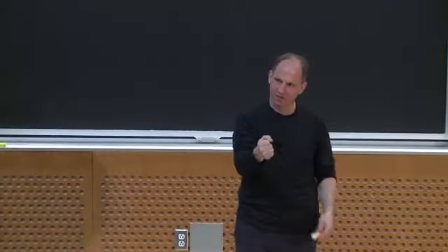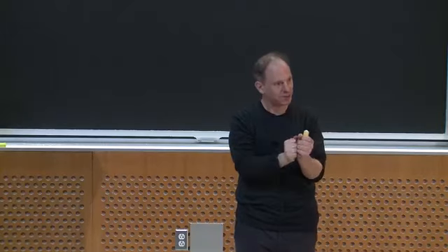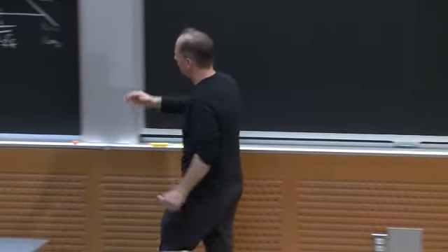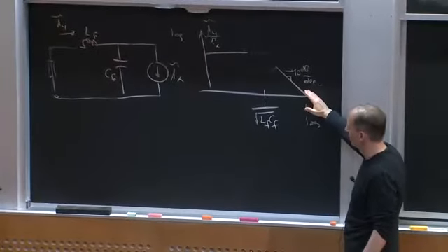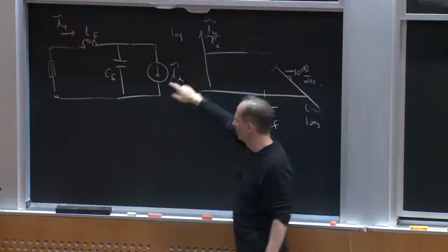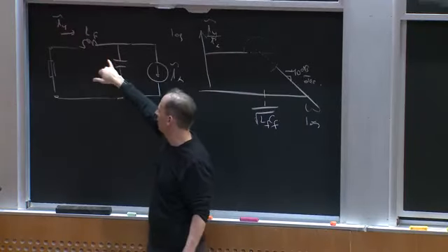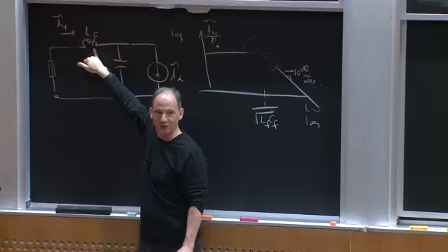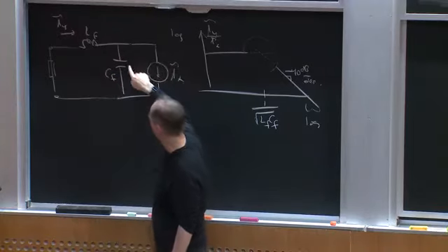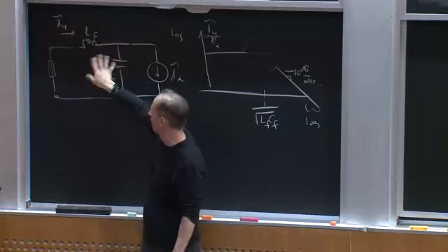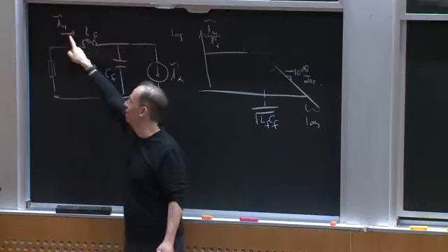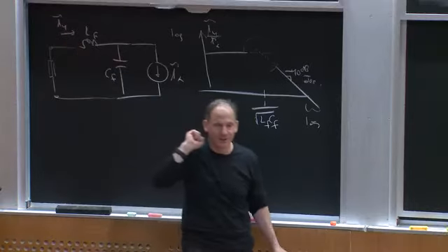I have an inductor in parallel with the capacitor at its resonant frequency. So while I get this roll off at high frequency, and I get all the current passed back at DC, basically at the resonance frequency, LF and CF look like an open circuit. If I start to draw any ripple current near the resonant frequency, I'm going to get huge circulating currents in the input, and I'm going to drive a big current IY back into my input.